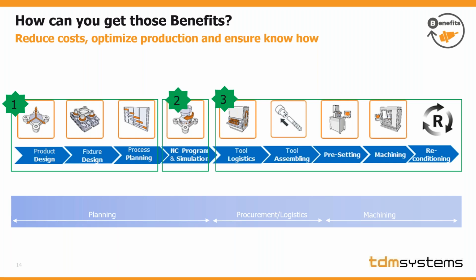And then the second phase, which looks really small, but for me is actually kind of the low-hanging fruit, the semi-quick win of planning, is programming. If you can create a reliable process from NC programming to simulation to machining, you can really reduce your tooling-related downtime. And of course, with smart design, you can reduce your costs tremendously. And then, of course, number 3, the obvious one, the efficient shop floor process. You reduce costs by having a transparent process, organizing your tools and equipment, reducing stock costs, and so on and so forth. These are the 3 areas where tool management has an influence.